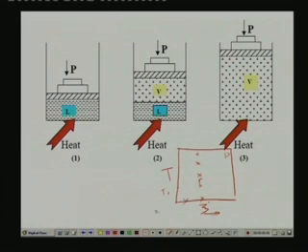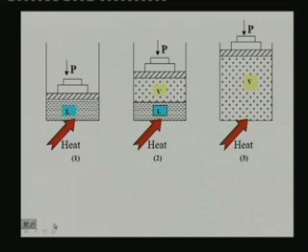Now, let us say that I repeat this experiment with another concentration. You find that exactly the same process appears, but these 2 temperatures will be different. So, instead of having temperatures like this, you will have another 2 temperatures. If you are starting this process at this initial concentration, then again you will have some other temperatures. So, if you carry out this experiment for different concentrations, you will find different temperatures, and if you join all these temperatures, you get what is known as dew point and bubble point lines for this pressure. So, let me show this dew point and bubble point lines.